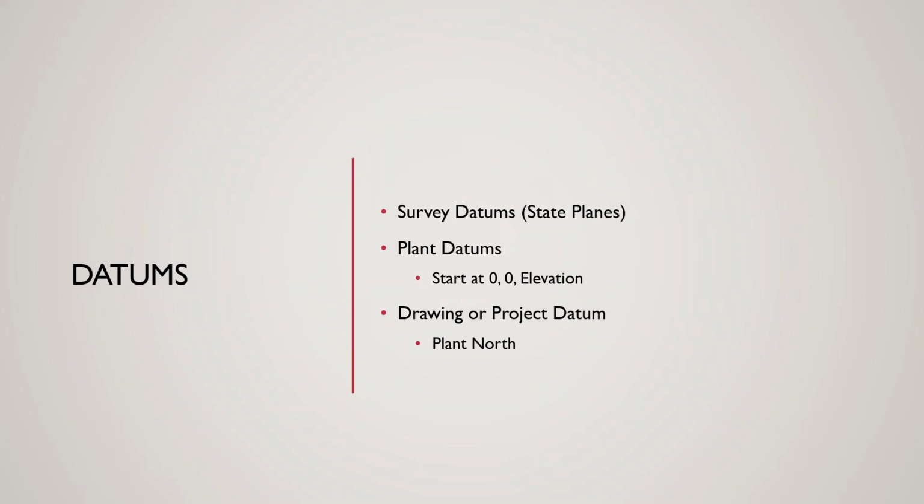And finally, my recommendation is if you've never done a laser scan and you just want to get it started and you're not sure if this plant is ever going to do another laser scan, then you can just ask the company that's taking the scan to register it to a project north. That means your coordinate system picks some area that will be 0, 0, and put north, north, or put your project north. So if a building is maybe cockeyed in space, maybe you want to rotate it so that its north is project north.